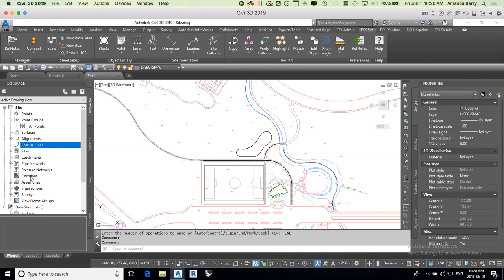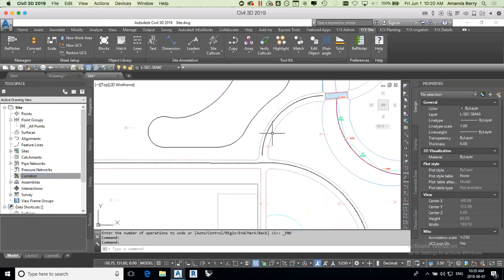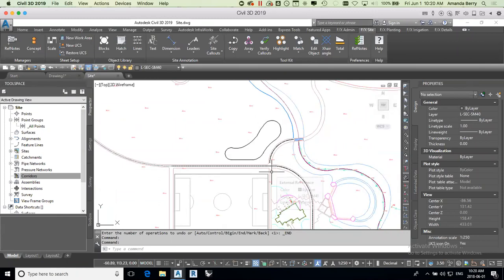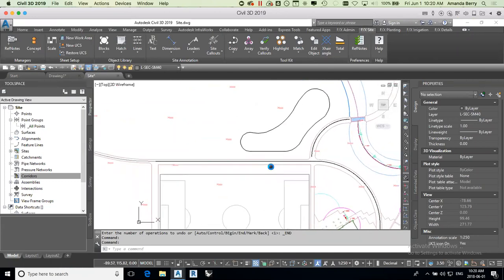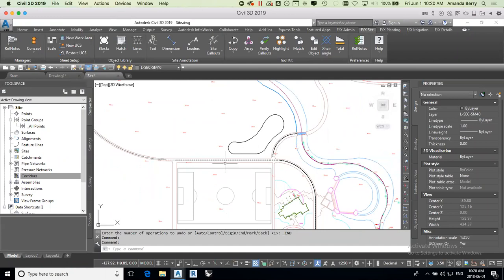I have tried using, and when I initially started, I was told to use corridors and assemblies. But I found in my own practice that it really hasn't worked well for me for smaller projects, especially parks, because as soon as you get into an intersection like this or pathways like this, walkways behave a lot differently than roads in that they frequently and very quickly change widths, and the widths aren't that big, and the intersections are very frequent and often not 90 degrees, and that becomes very complicated when using corridors and assemblies.